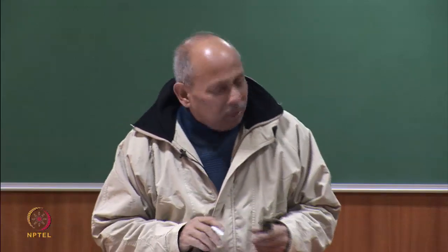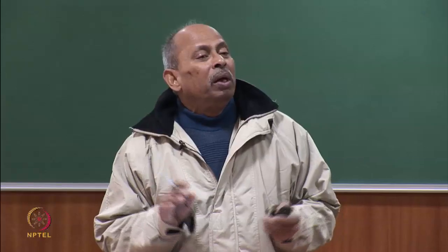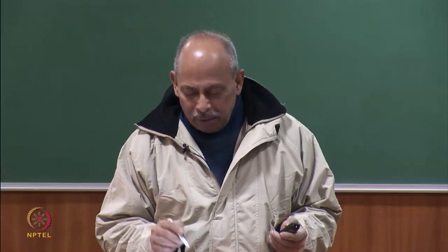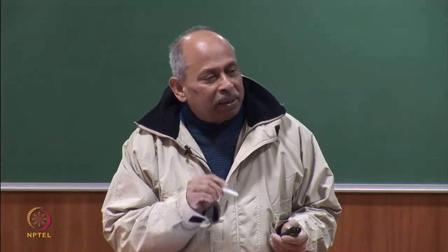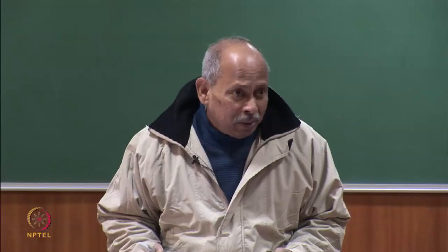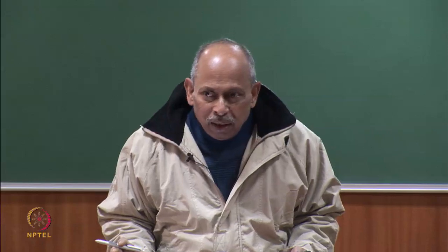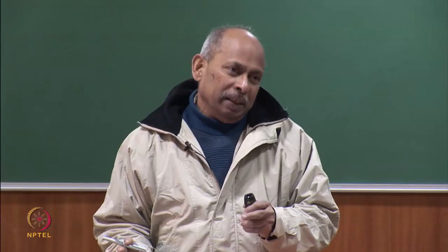Now, what is my unknown? The inside temperature, gas temperature, which changes with time. So, time temperature curve, if one wants to find out, one will have to solve that heat balance equation, because Tg, the gas temperature, is unknown, outside temperature is known, and one can solve for this. Now, this solving would be really complicated because it is a non-linear equation. I am not going to do that for you, but I just want to say people have developed such models, and CFD model uses this.